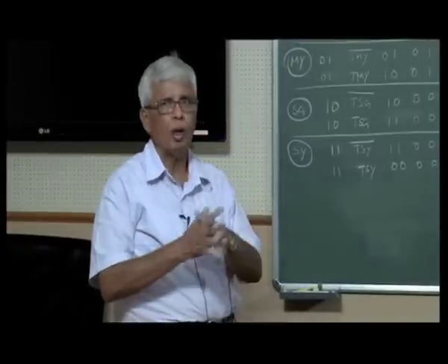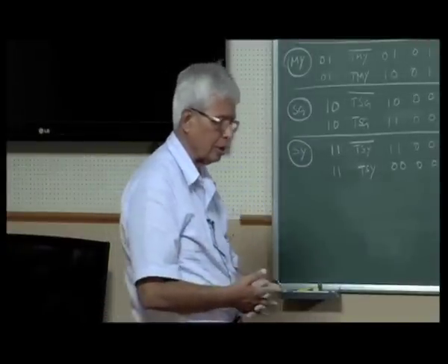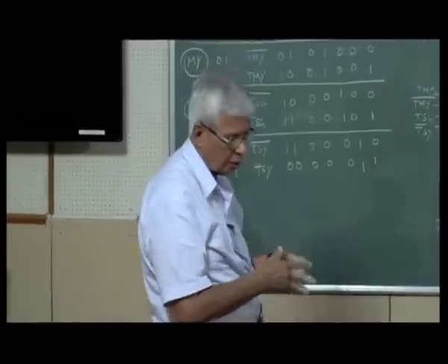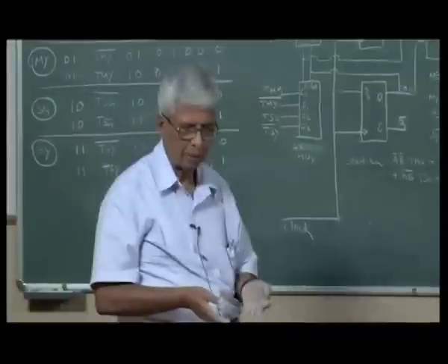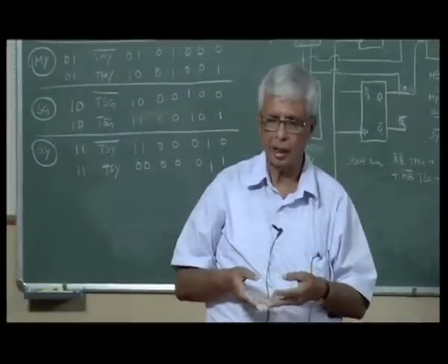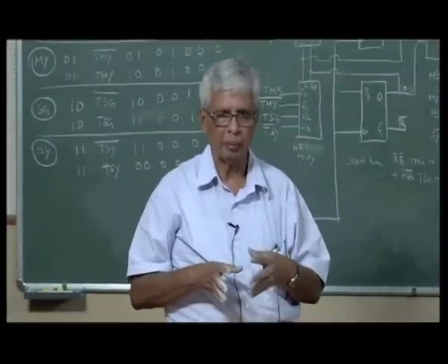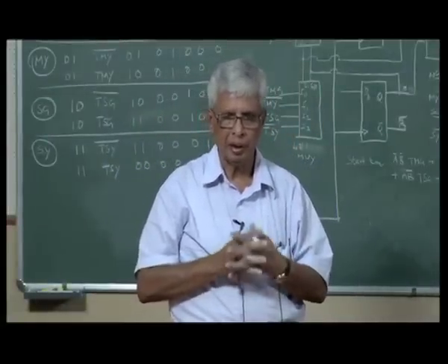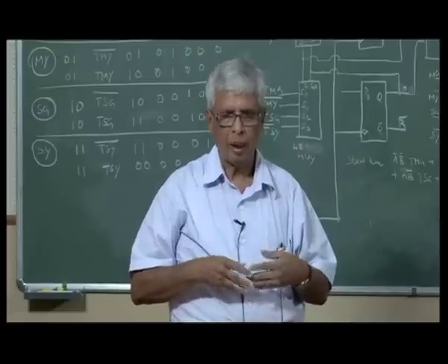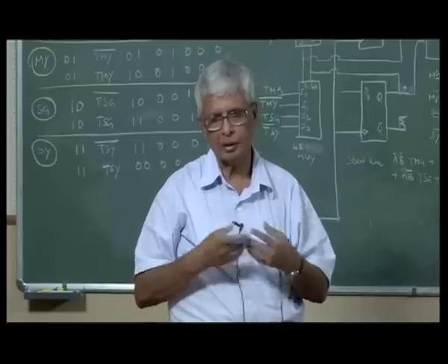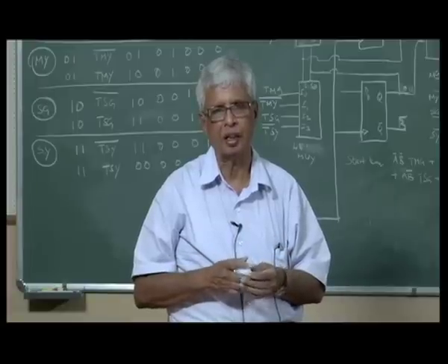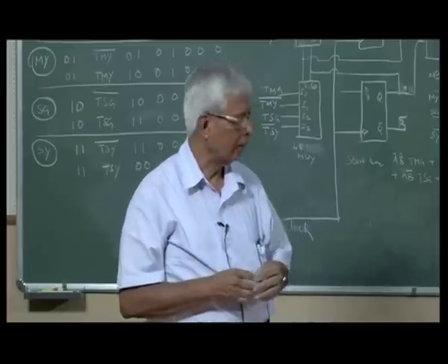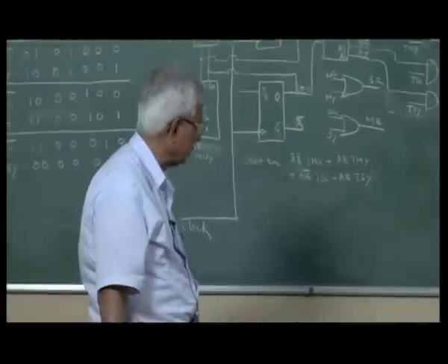You don't have to always do ASM. You can also do state machines. Or if it's only combinational logic, you can use multiplexers, programmable array logic, PROM, PAL, PLA, etc. Similarly, if sequential without combinational, you can have counters, registers, shift registers, and all that. With that, we complete the design process.